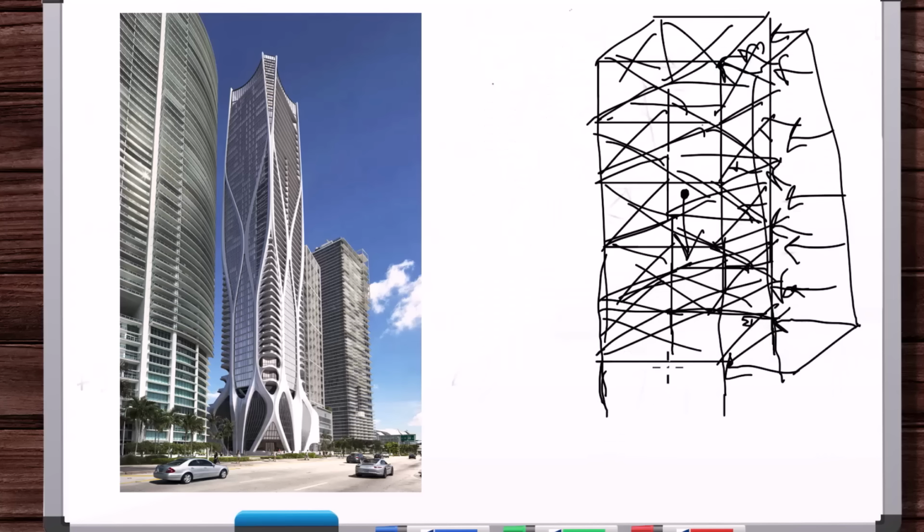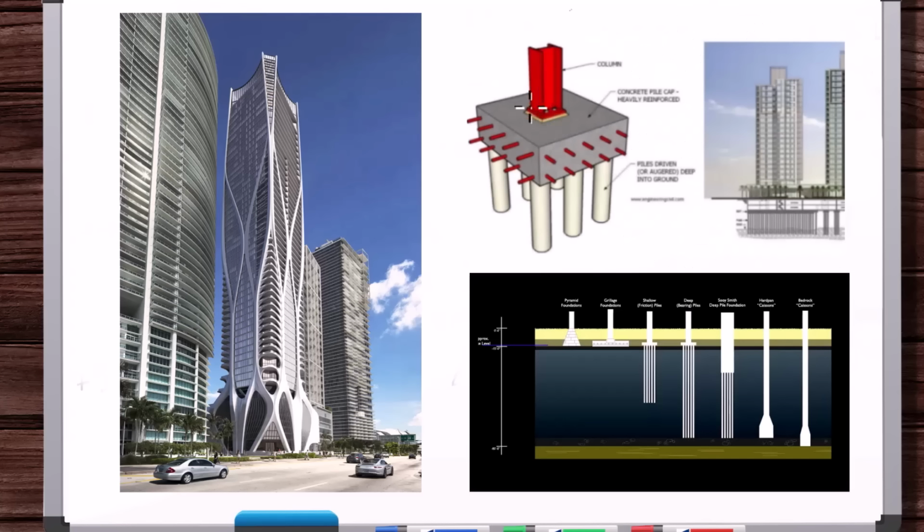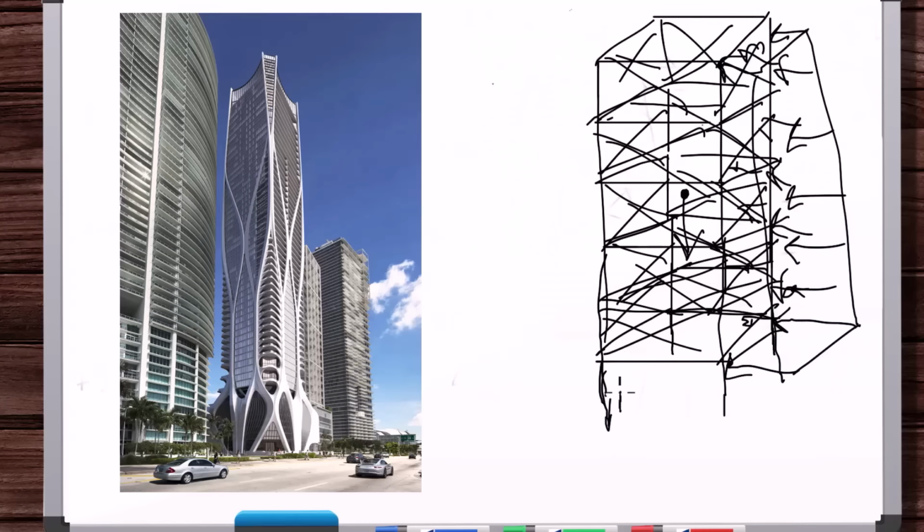So at each one of these locations, let's say there's only 4 locations that are going into the ground that are supporting the structure. Well, you could unbolt it and remove it, or you could make a cut here and remove it. You could do whatever you want. But let's say you unbolted it, for example. You would have bolt force, bolt force, bolt force, bolt force. And that's the free body diagram. That's it. Those are the only contact points between the structure and the environment. All these other forces are internal forces. That's it. It's that simple.